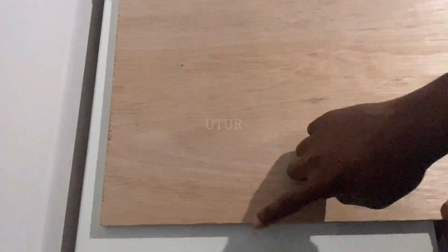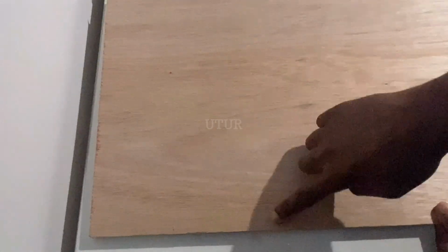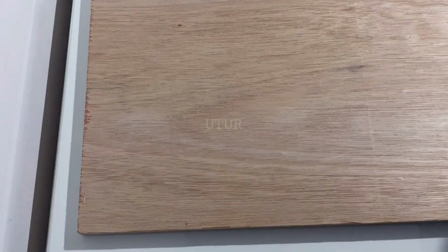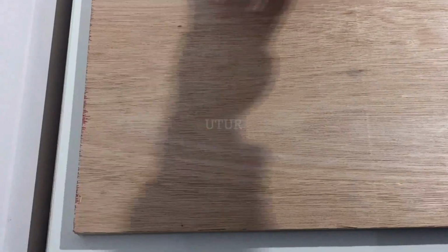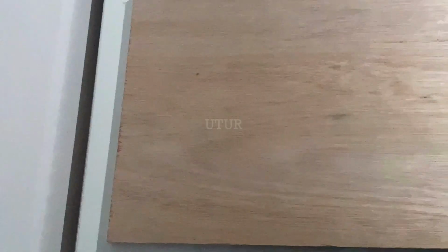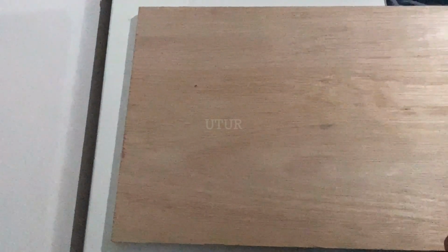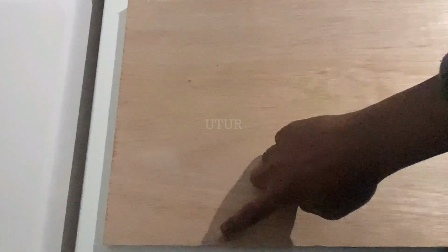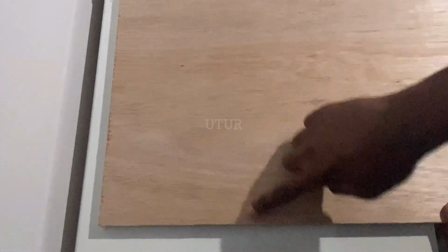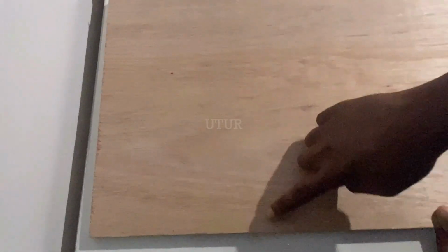An increase in the amount of teeth essentially means that it will take a bit more time for you to cut through your plywood. But it does a bit of cutting, a bit of ripping, not as your dedicated cross-cut blades or your ripping blades. But you will get better quality cuts with the composite blades. So ideally, a composite blade with a 60 tooth threshold value should be able to get quality cuts off of the plywood. And so now let's move on to some more simpler woodworking.